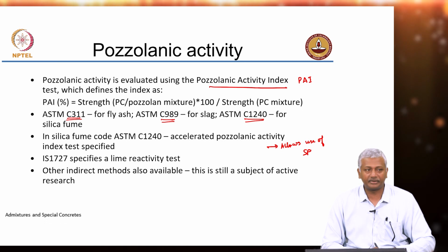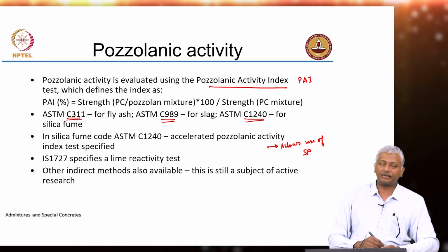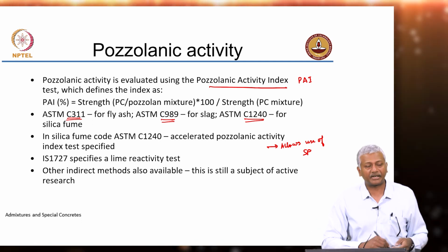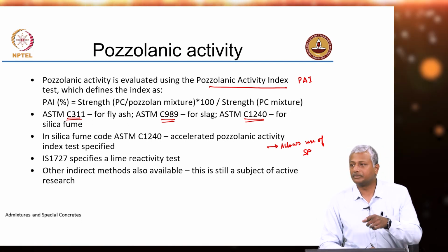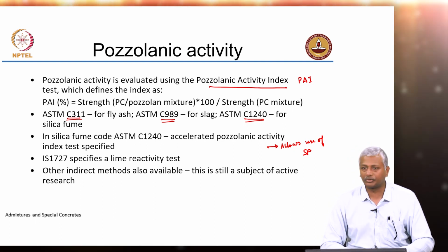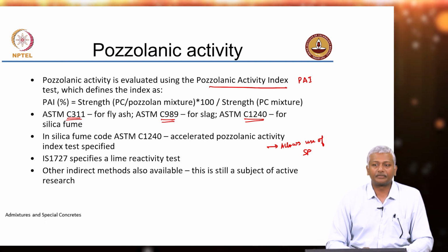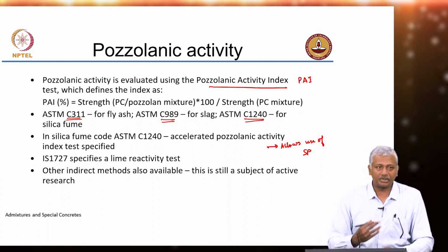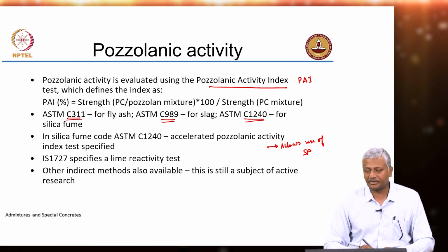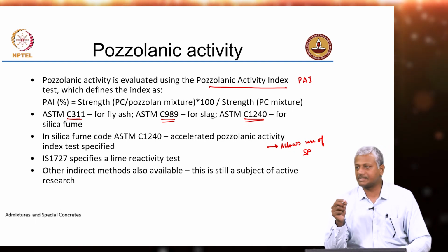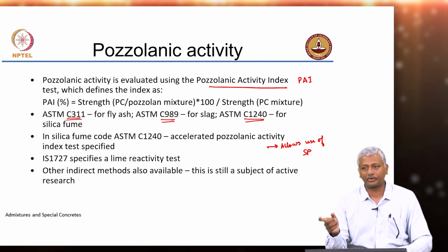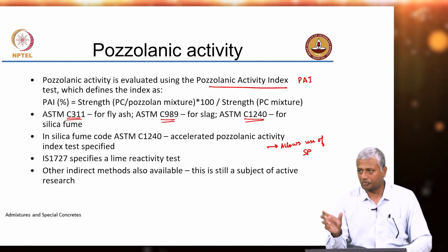Now, this is again a very common issue that we see between the practices in India and the practices in Europe, for instance. So, strength of cement in India, 43, 53 and all that, how do you determine the water content for those strengths? You determine it from the standard consistency. There is a formula that you need to apply, 0.85 times this value. So, you determine the standard consistency and use that to determine the water to binder ratio required for your strength test to cast the cubes.